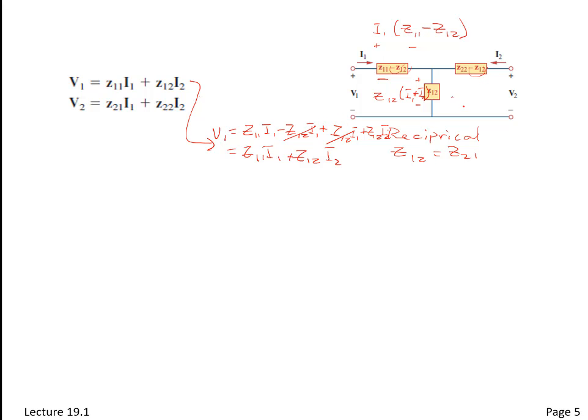So this is for a reciprocal circuit. What does this mean? Let's say these were resistors. This means I could represent this pair of equations as a simple T equivalent circuit with resistor values of this amount. They don't even have to be resistors; they only have to be impedances in this amount. As long as they're reciprocal, I can use this T equivalent and off I go.